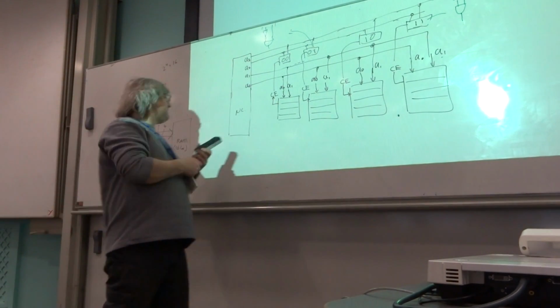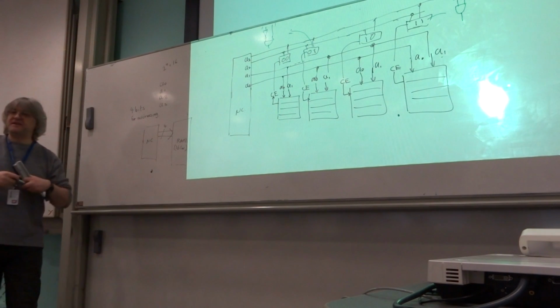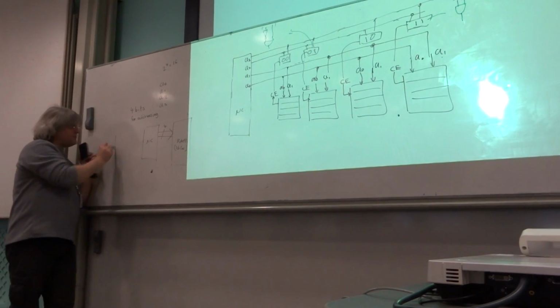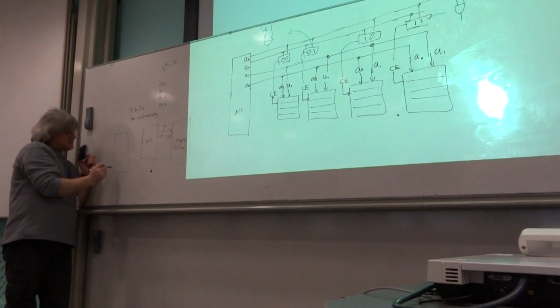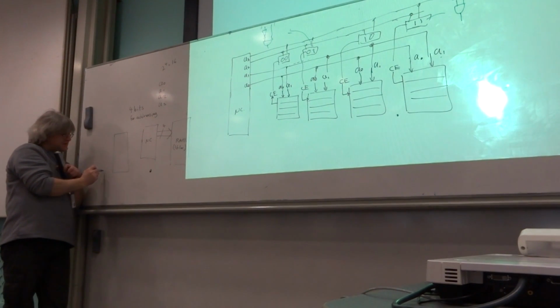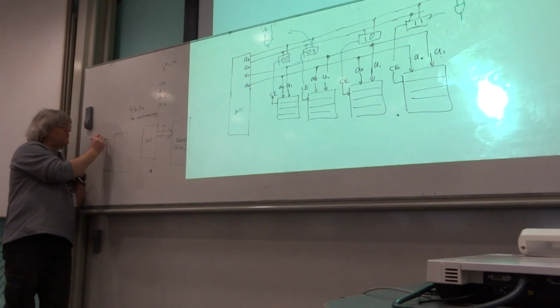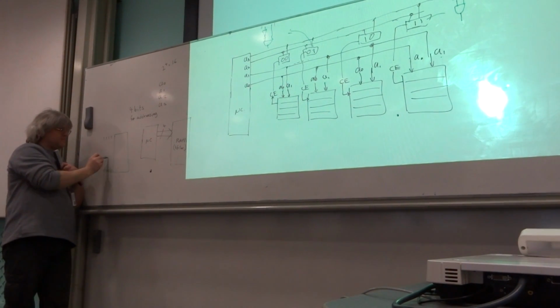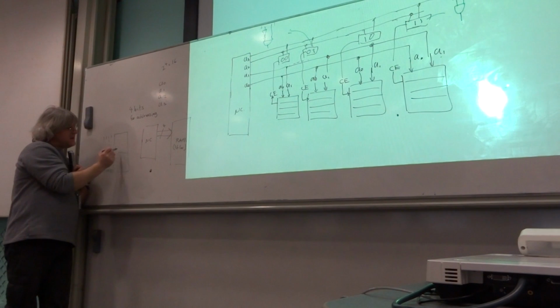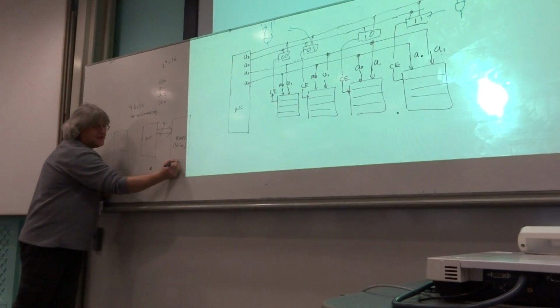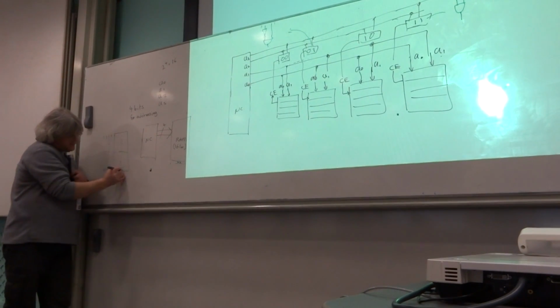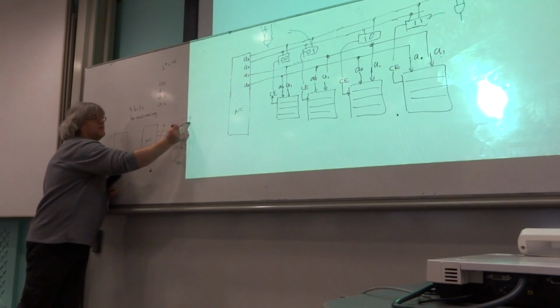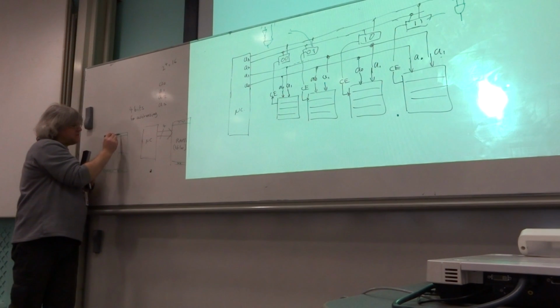Now, if I was to draw the memory map of this device, so this RAM, I have 16 locations going from 0, 0, 0, 0, this is all in binary, to 1, 1, 1, 1. Okay, and the RAM occupies the whole thing. So that location there, XX, would be that location down there. This location up here, YY, would be that location up there, YY.